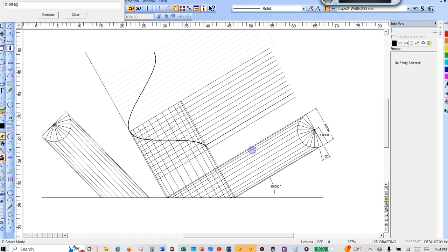All right, this video is going to be about developing a pipe template for just a flat bevel. This is a pipe that's sitting on a flat surface, and I'm going to show how to develop it out. This is the rolled out version. It's actually half. We'll do half of it, and then the other half just reflects. It's the same, just reflected.